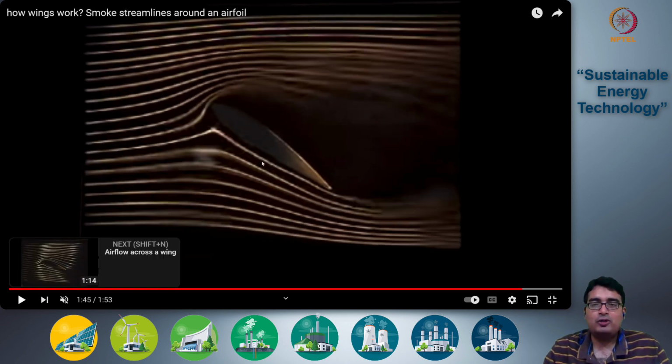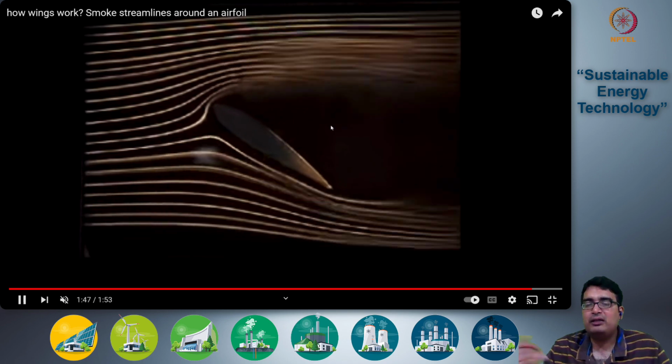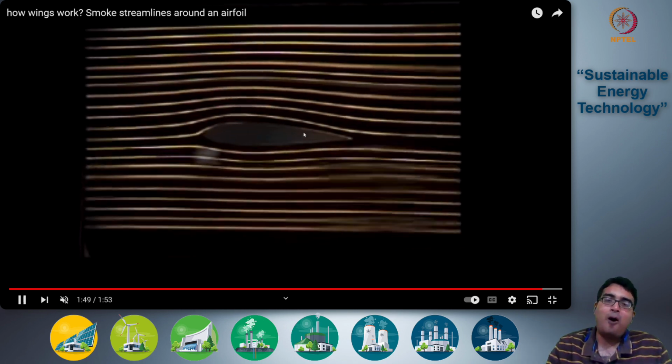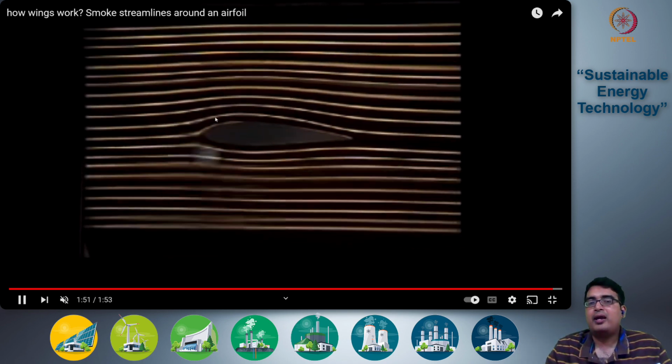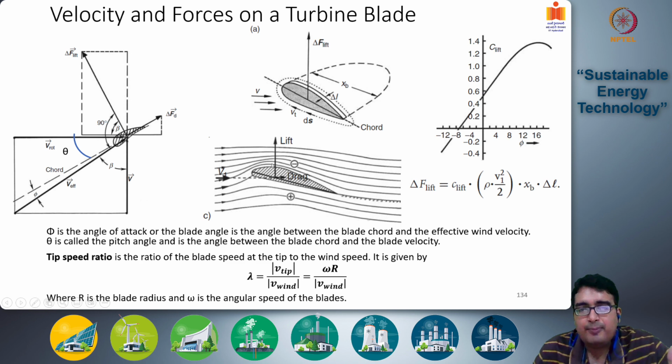So in this detached mode, the cross sections on both sides are relatively the same. Only if the flow is flowing through the contour do you have a higher cross section here and a deceleration. Okay, this is no longer happening, and so there is a sudden loss of the lift force. So there is an optimum angle of attack around 8, 10, 12 degrees, beyond which the lift force stops.